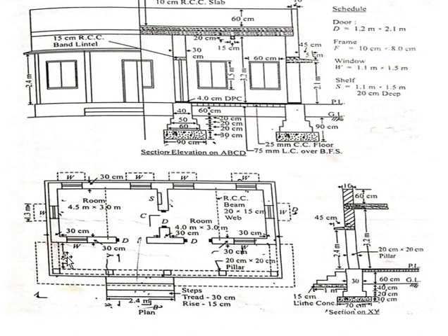This wall is 20 centimeter thick, so half thickness is 0.2 by 2, plus this entire length plus half the thickness of this wall. Here we can see this wall is 0.3 meter thick while this is 0.2 meter. Therefore this particular portion here is 0.1 meter. Similarly on this side it will be 0.1 meter.